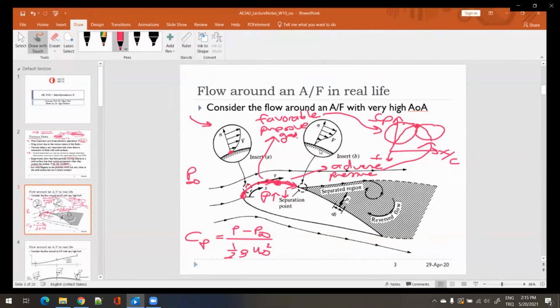But here, the fluid particles are spending their already existing kinetic energy and momentum to move against an increasing pressure in an adverse pressure environment. Depending on the level of their kinetic energy, this can happen up to a certain point. They can move and move, but every time they move against an increasing pressure, they keep losing more and more momentum.